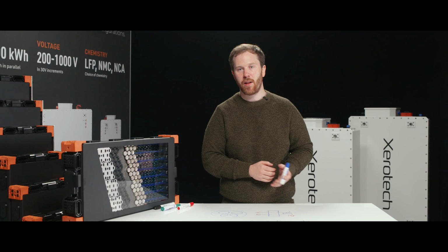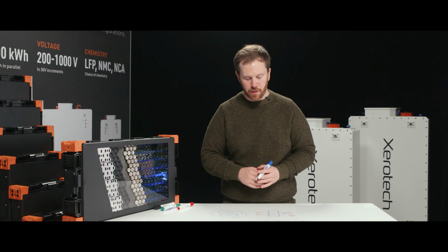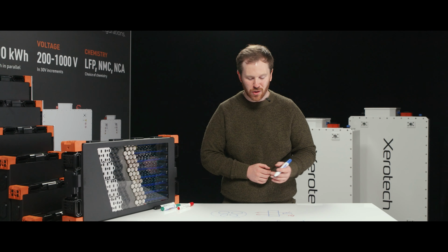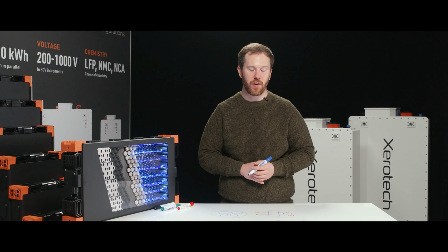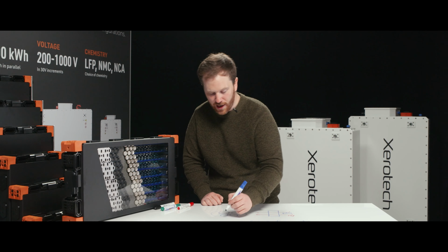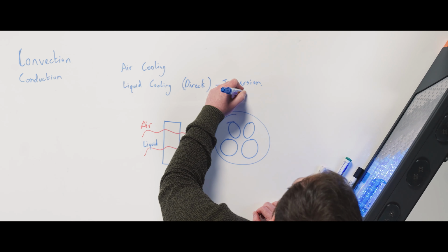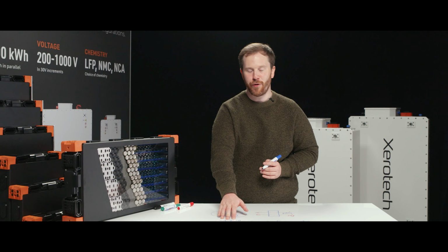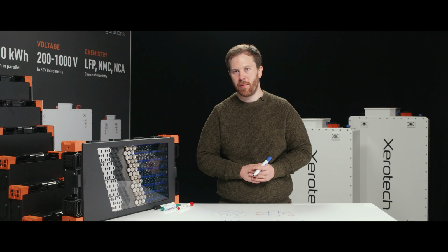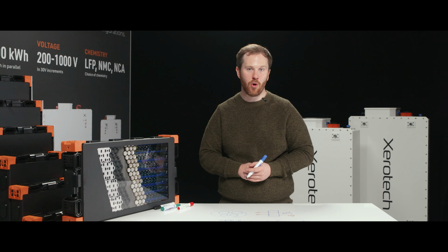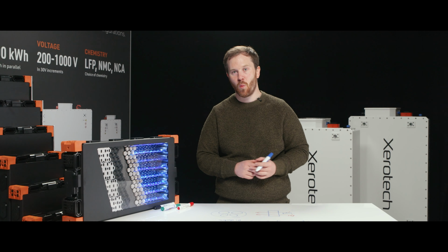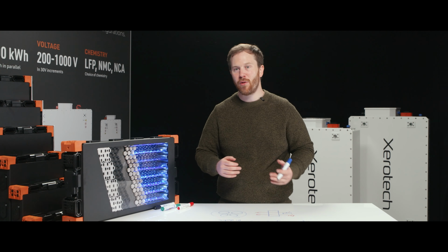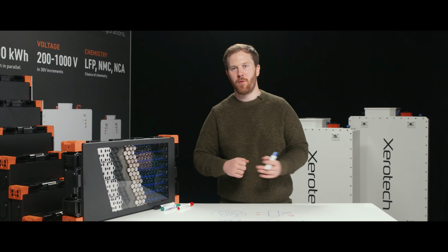You benefit from the heat transfer capability of the liquid, but unfortunately most liquids are electrically conductive, for example water. So that generally rules out water for these types of systems. Instead, they use something called a dielectric. Basically means it doesn't conduct in most cases. The dielectrics, unfortunately, have a much lower heat transfer capability, usually about half, if not lower, than that of water, and have much worse thermal properties in terms of thermal conductivity and other factors. They're generally more viscous as well, which means it takes a lot more power to pump them.